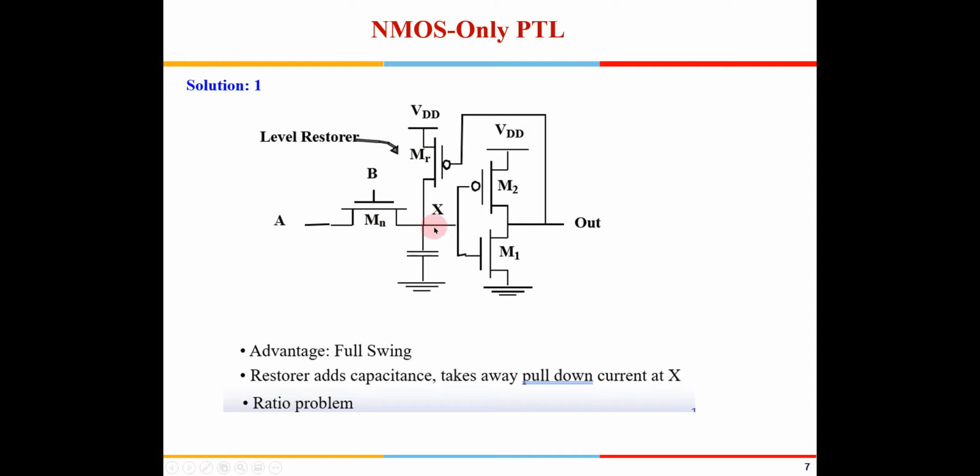In pass transistors, if you have a larger size, then the delay will be lesser. So we'll see how to calculate the delays. That's all. It is not a ratioed logic, like you don't have a PMOS and NMOS ratio, things like that. In this particular circuit, obviously the NMOS has to be kept much stronger than the PMOS. So through simulation also we can fix the value. I'll show you one graph which will show the effects.